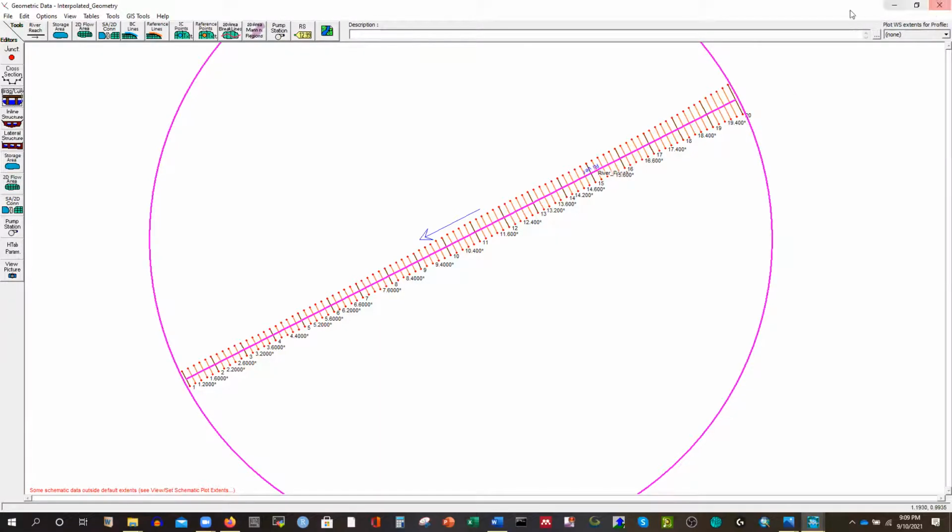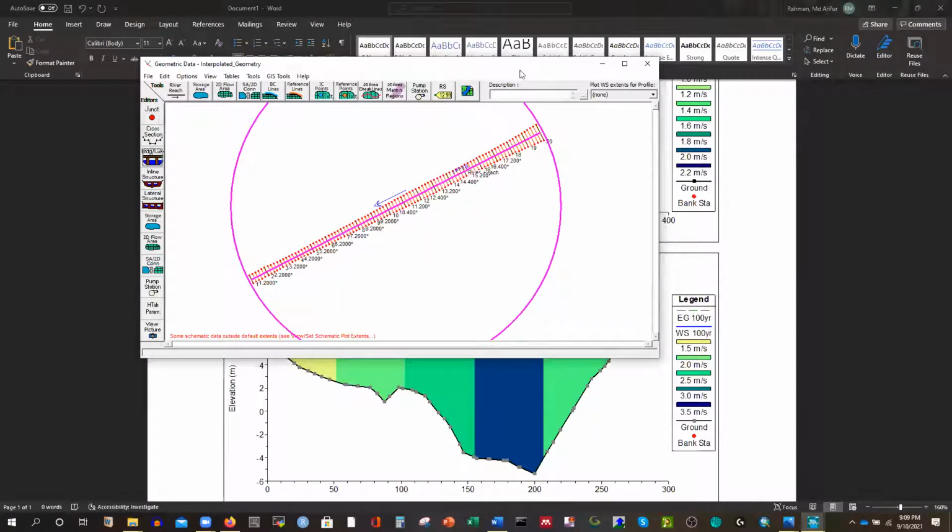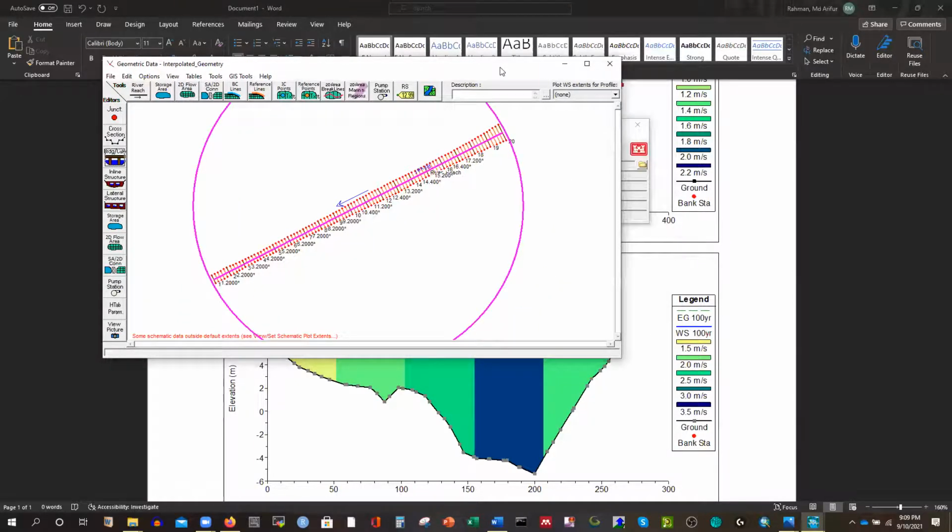There will be different types of scouring. From a bridge scour, it is called a pier scour from bridge pier, and there will be scour from abutment of the bridge, and there will be some local scour as well. So we'll combine them together and we'll add them up, and then we'll calculate the total scour, and based on that scour, if it's necessary, we'll have to provide some piling while constructing this bridge or not. So that's the idea. We have to be able to calculate everything.